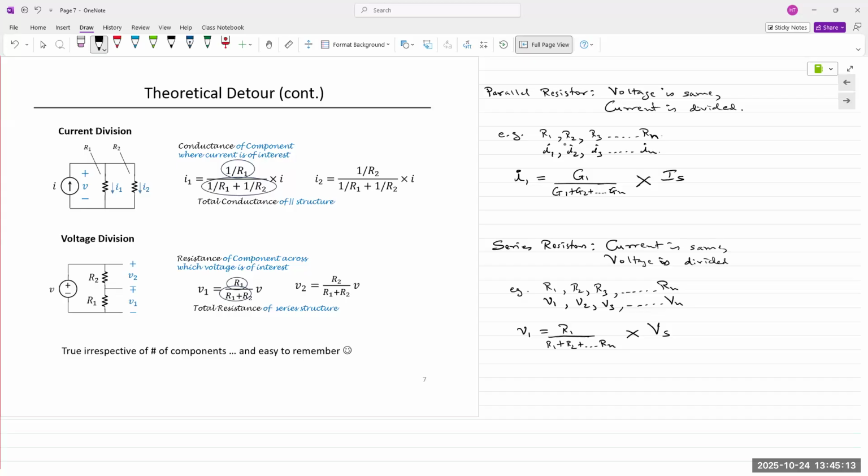That was in parallel with some in series. Yes, that is correct. So the question being asked is, if we have 5 resistors in parallel and there was a 6th branch in parallel, and that 6th branch had multiple resistors in series, then yes, we could combine all of them and reduce it to one single resistance. And so that 6th resistor would be in parallel to the rest of the 5.